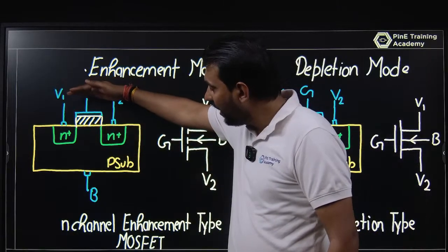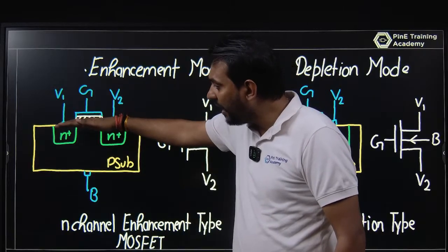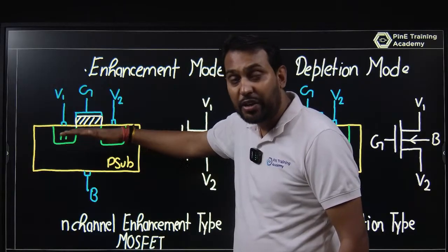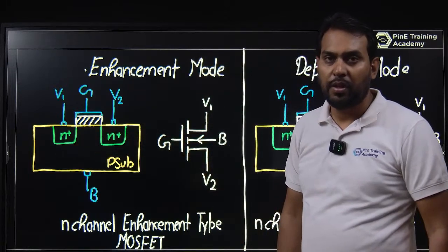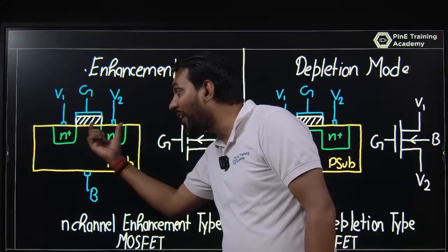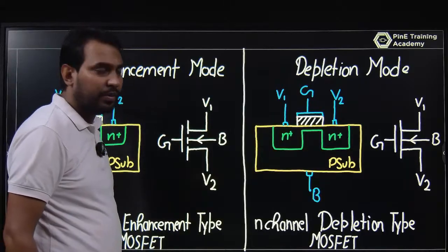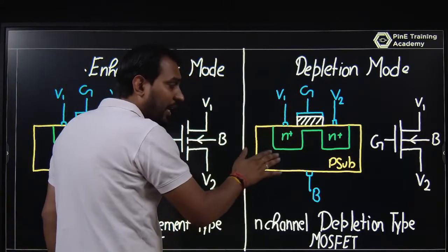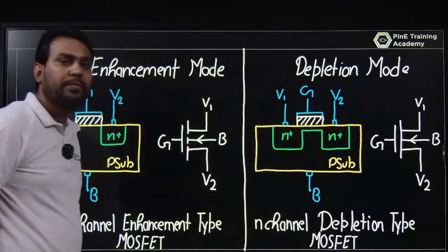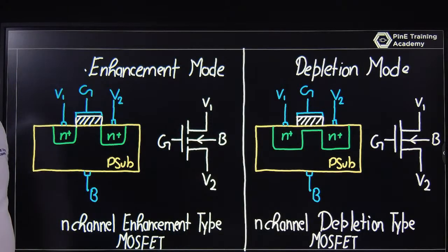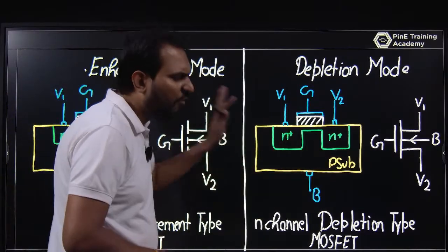This is metal, this is oxide, that is silicon dioxide. Okay, and after the silicon dioxide you have the silicon. That is metal oxide semiconductor. In enhancement mode, the channel is not connected. Similarly, if you talk about depletion mode, metal oxide semiconductor, the channel is connected, the N plus regions are connected, the channel is already present. That is called a depletion mode MOSFET. And in that very basic part, both are symmetric in nature, everything is the same.